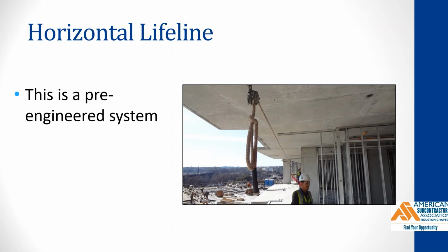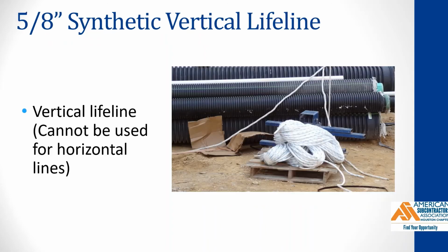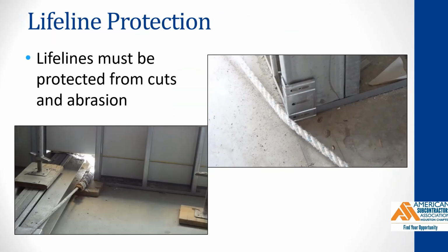The horizontal lifeline is a pre-engineered and approved system. Follow the manufacturer's instructions in installation and loading. 5/8" synthetic vertical lifeline cannot be used in a horizontal application. Lifelines must be protected from cuts and abrasion.